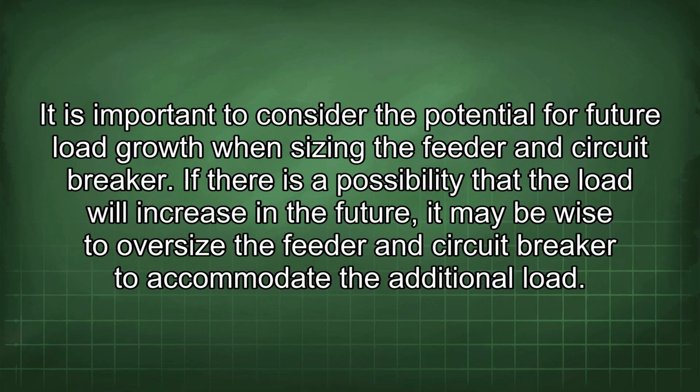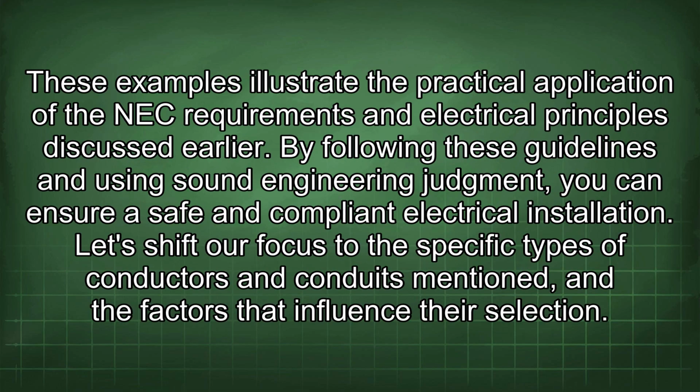It is important to consider the potential for future load growth when sizing the feeder and circuit breaker. If there is a possibility that the load will increase in the future, it may be wise to oversize the feeder and circuit breaker to accommodate the additional load. These examples illustrate the practical application of the NEC requirements and electrical principles discussed earlier. By following these guidelines and using sound engineering judgment, you can ensure a safe and compliant electrical installation.